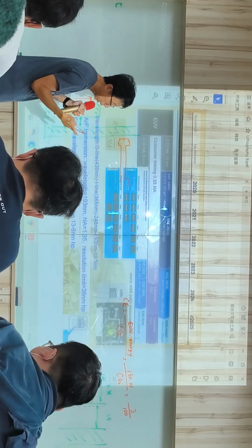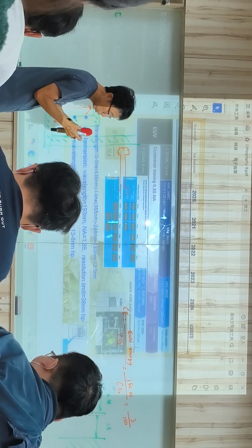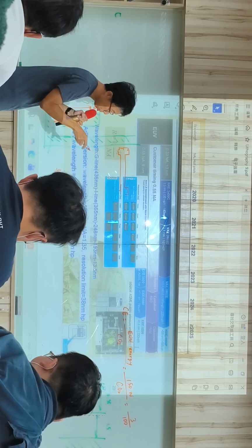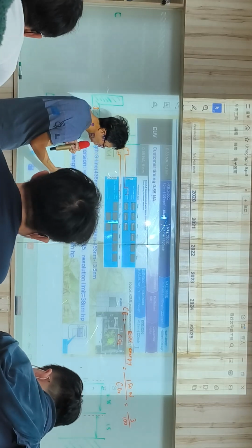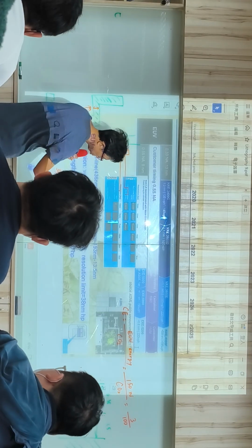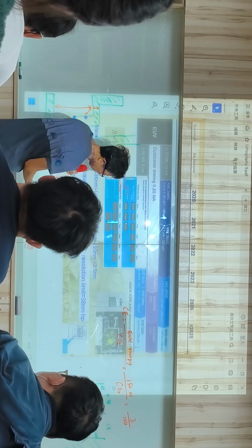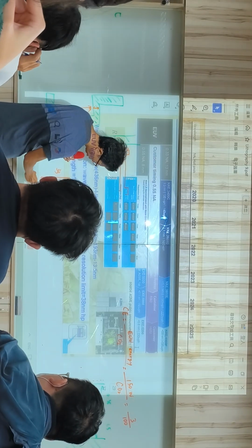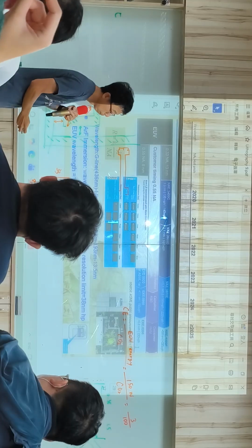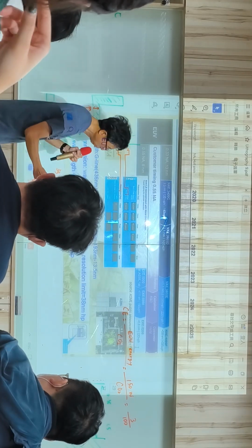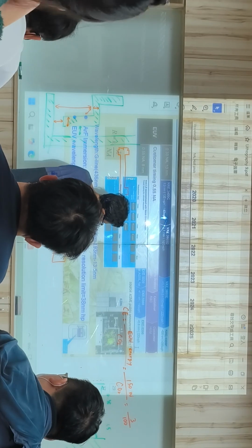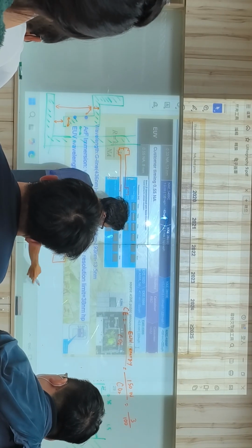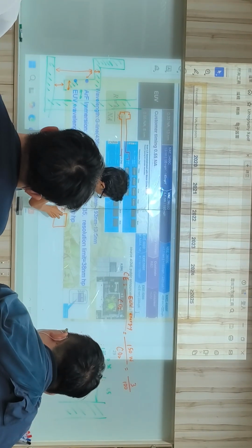The reason is that, as I told you, the high NA uses a central obscuration, so they cannot use a full field. Also, in the y direction, it becomes 8X. On the X, it's still 4X. So what does that mean? It means that if you have a contact, just for simplicity, make it 20 by 20.